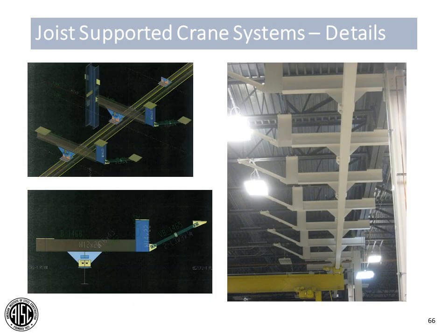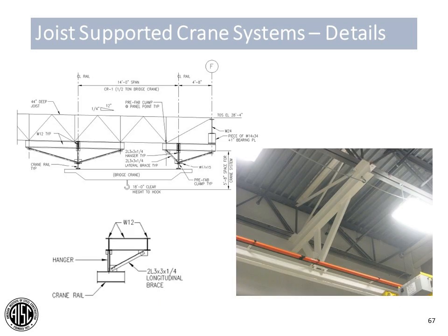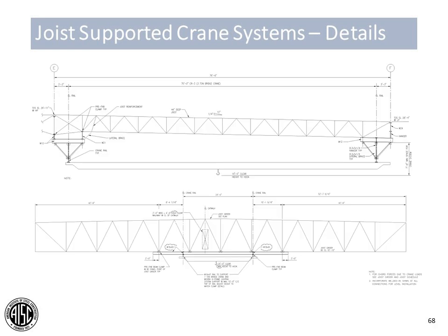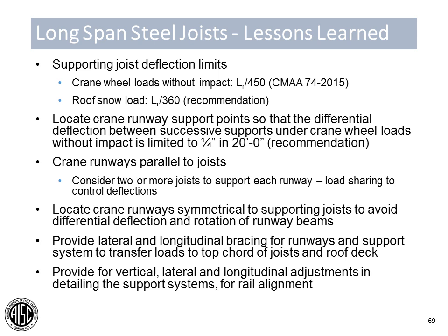And then just a couple more lateral brace details, lateral support details for your runway systems. Here we've got a sloped roof system, so we have to have supplemental steel, again, distributing the forces to panel points within these joists. And then we have long span joist or truss systems. These can be a substantial challenge due to the installation tolerances of the steel as well as of the runway itself.